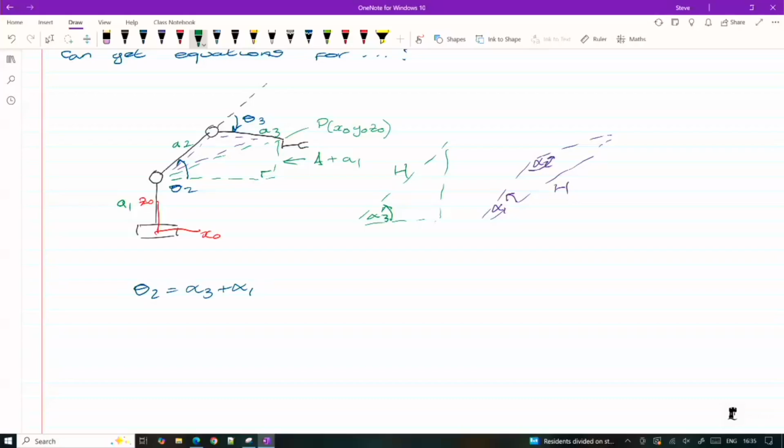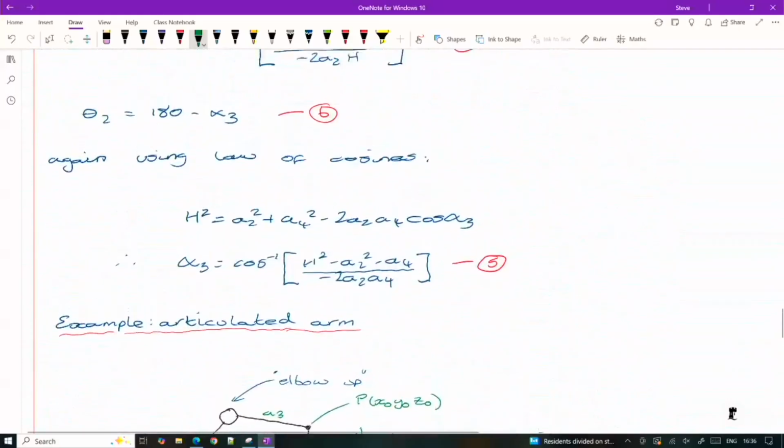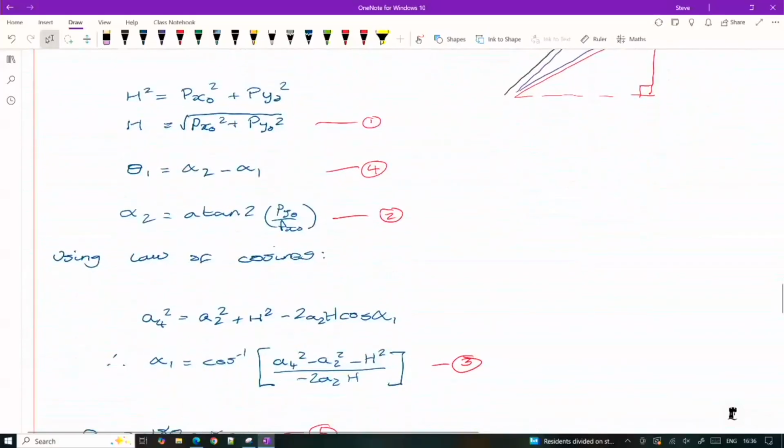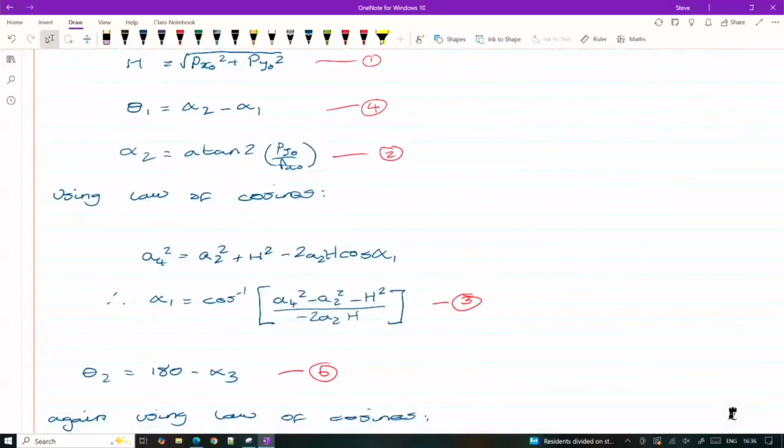Just remember, one thing for the coursework, we want you to solve the inverse kinematics for the Dobot, so you can't use the functions that do that for you, where you simply say position the arm at x, y, z, okay? You want to calculate the angles to do that for you, okay? So you'll end up with a set of equations such as this that you will have to solve within the Dobot programming environment in order to give you the joint variables that you need to position the robot at certain points in space.